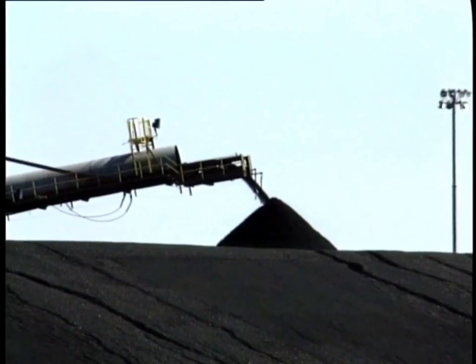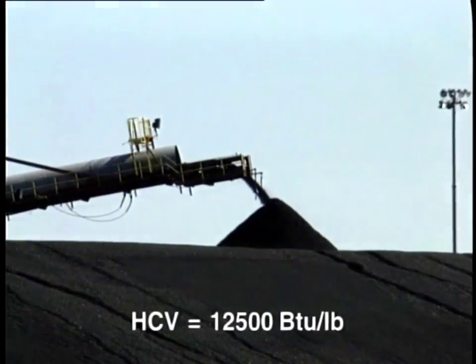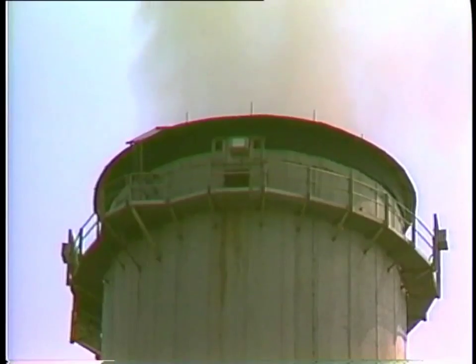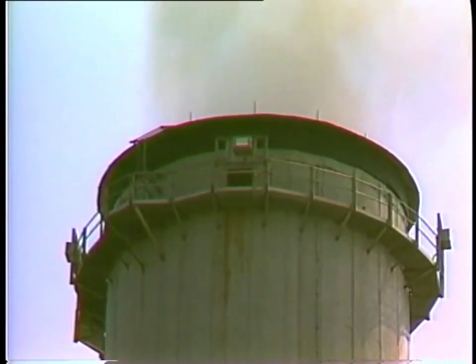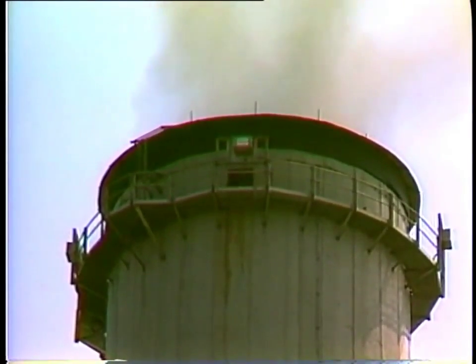When comparing fuels and looking at the efficiency, it's essential that we make ourselves aware of exactly which value for heat content is being quoted. In the USA, it is usual to quote the higher calorific value. The logic of this is that we have to purchase all the fuel even if some of the heat cannot be recovered. In fact, as we know, other heat losses are far greater than this amount.